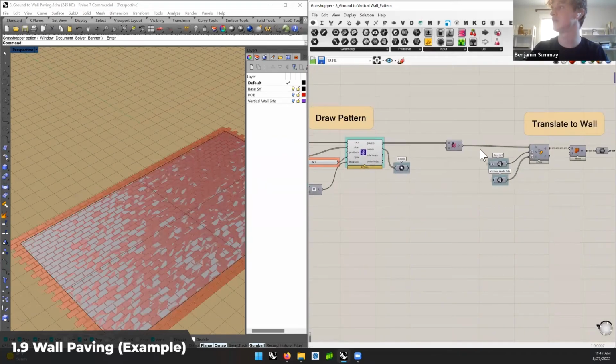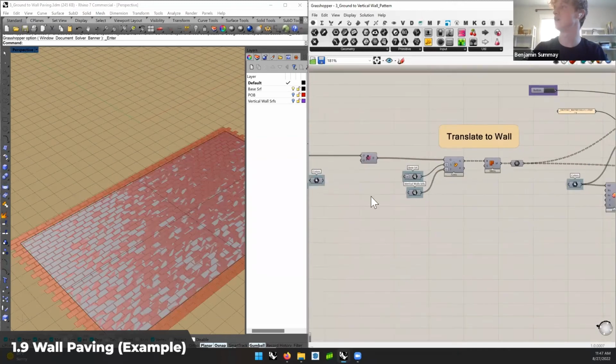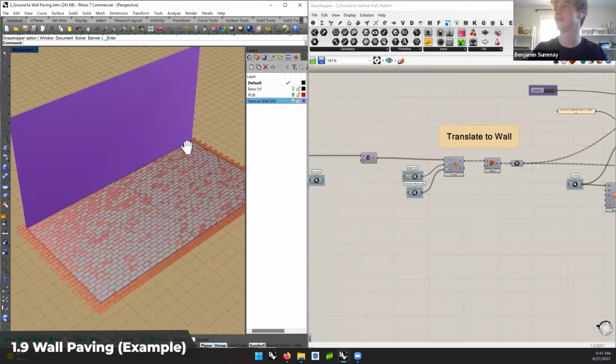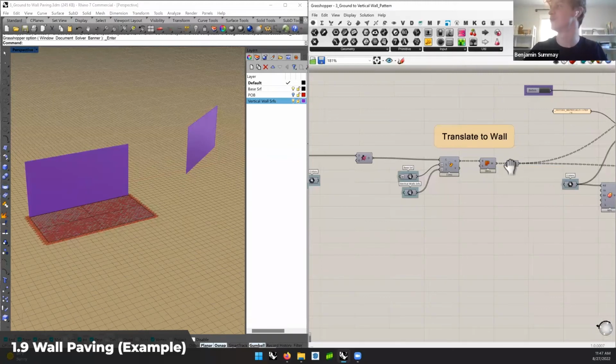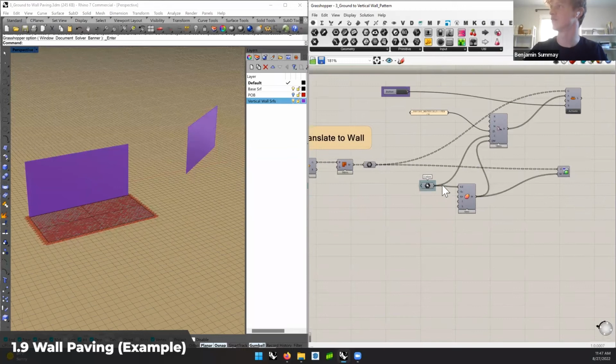And then what we're doing is we're taking that and using just some simple embedded components within Grasshopper to map that surface onto a series of other surfaces that we have here, these 2 different ones, and converting those again to a mesh because we love meshes. Meshes are smaller and easier to deal with, especially when you're dealing with hundreds of these little pieces of geometry. I believe we have 1,890 mesh bricks here that are being used for the wall. And then we actually have a workflow here for baking those out with their appropriate colors.